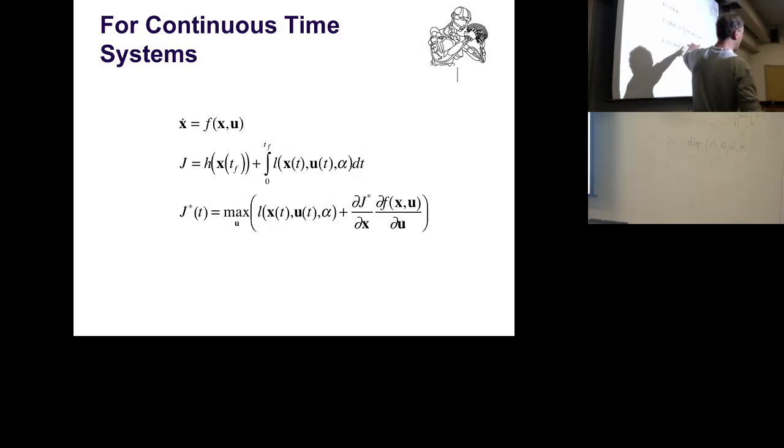If you do LQR in continuous time, you plug in your cost function. You know your model, which is now this kind of continuous model. If it's linear, it's easy to solve. If it's not linear, you have to locally linearize at every time step, and you get the same solution, where the gains multiply the state x, and that's your motor command to get this linear gain system.